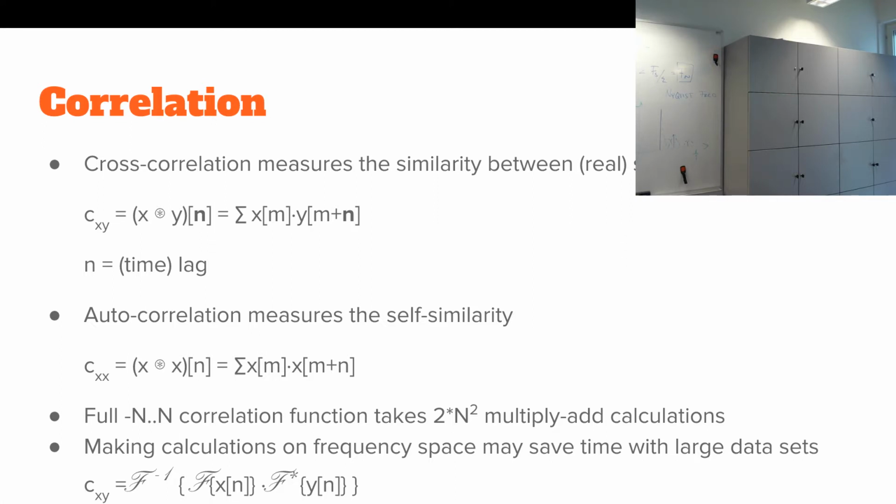So you have random noise here, but if you do a correlation of this part of the signal with the rest of the signal, you will find the highest correlation. That function gives you the cross correlation function. It gives you the highest level where there are similarities. So you take the highest one, and that's your echolocation.